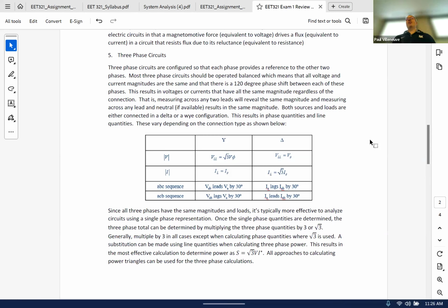But three-phase power is just taking 3 single-phase power sources and referencing them together in either a delta or a Y, so that you have all the power you need. Each one of those phases can provide a path back, a reference back to get to that power supply. We only talked about delta and Y. There are other configurations, but they're more advanced and they have to do with grounding or some special filtering. So we really won't get too focused on systems that are not delta or Y. We'll focus on the deltas and the Ys.